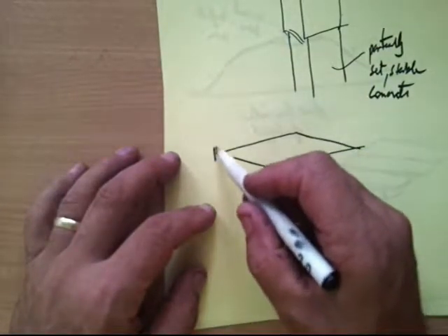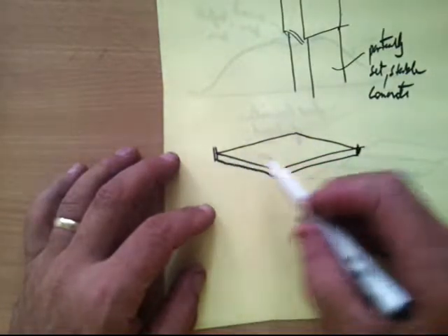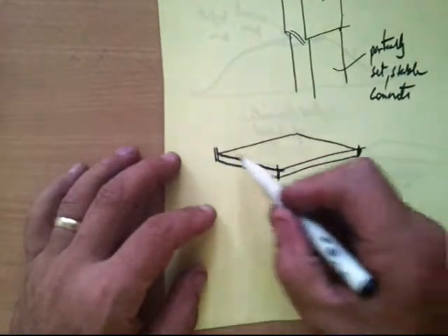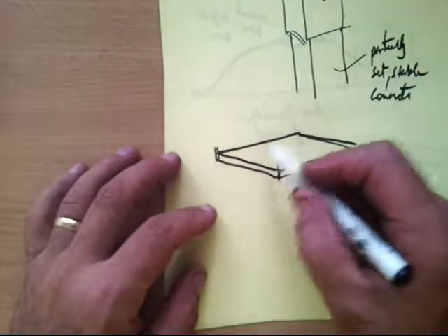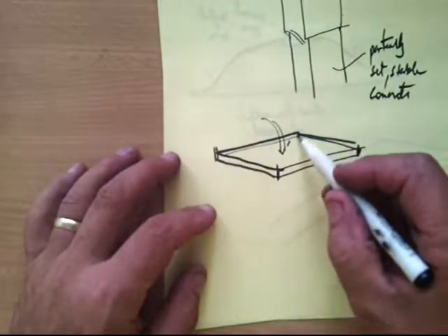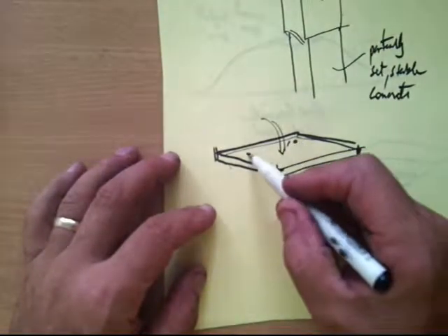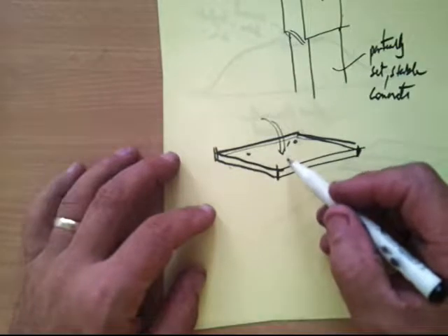Now, I did mention to you that on large sites where you want to create some big walls, especially for factories, workers will often create the slabs on site. So they'll lay out some pegs on fairly straight ground, make sure that it is straight, and put in some formwork around like that, and then pour in concrete in here and set a slab.